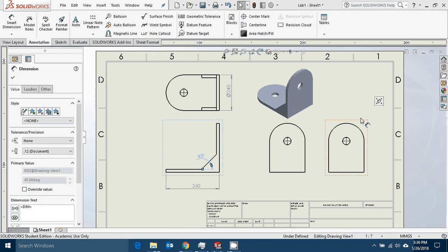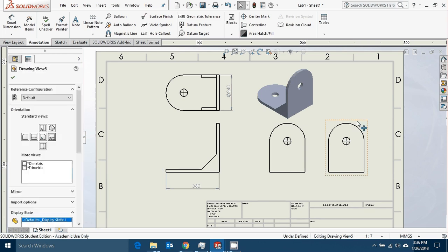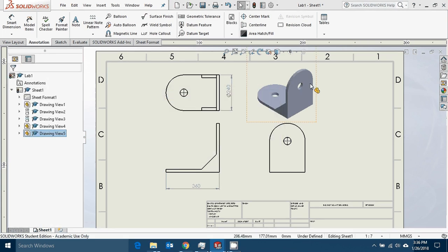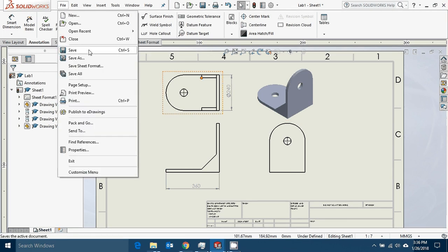One further thing, when you're dimensioning, you should not have any dimensions on your isometric view. Okay, your isometric view is just there to give a 3D representation of your part. Unless absolutely necessary, you should not have any dimensions on this view. Your dimensions should stay on the top view, front view, and right view of your part. Once you're done that, just save your draft file.